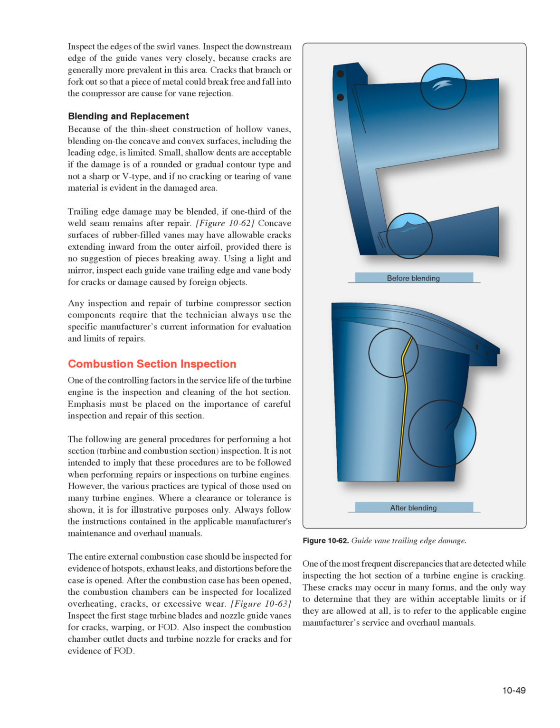Combustion section inspection. One of the controlling factors in the service life of the turbine engine is the inspection and cleaning of the hot section. Emphasis must be placed on the importance of careful inspection and repair of this section. The following are general procedures for performing a hot section, turbine and combustion section inspection.